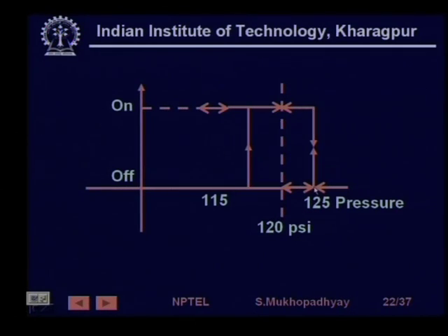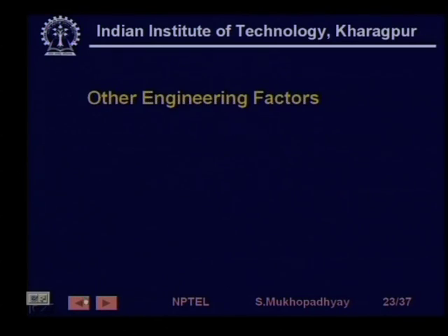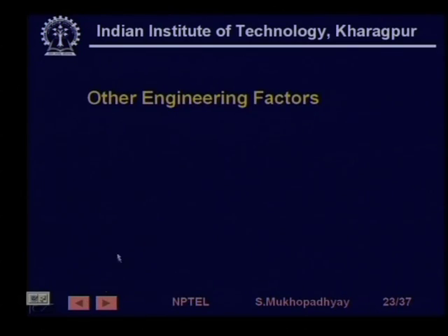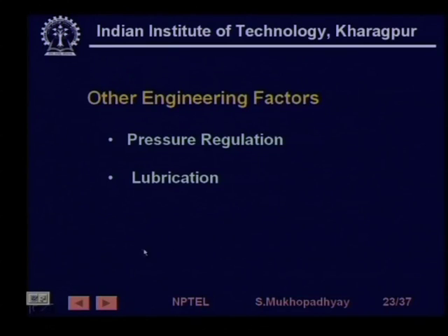So, you come here, and then again as the loads draw the air, the pressure will fall. So, you actually move around through what is called the hysteresis rectangle. This is the way of controlling the reservoir or the accumulator.